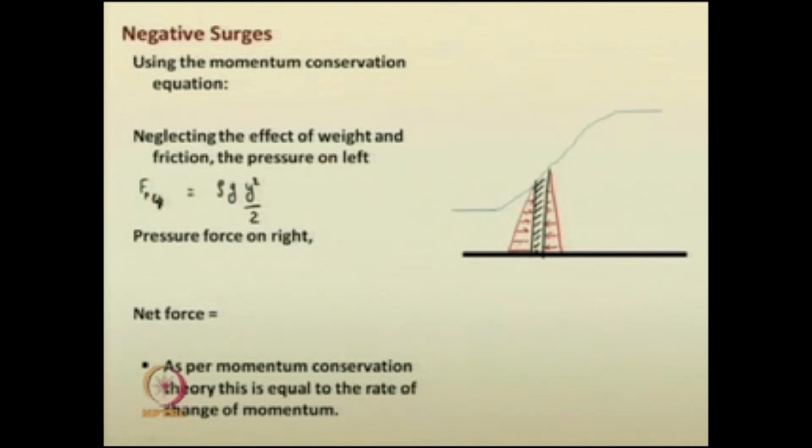The pressure force on the right will be rho g into y plus delta y whole square by 2.